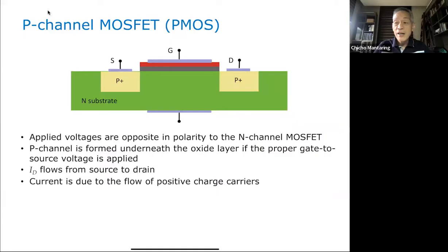Okay, so that is your N channel, no? So I just want to mention this. If you have an N channel, you have a P channel. The N channel, we also call it an NMOS, an N metal oxide semiconductor transistor. The P channel, we call it the PMOS. In the P channel, your substrate is N-type instead of P-type. Your source and drain islands are P-type. Okay. Then everything else is the same.